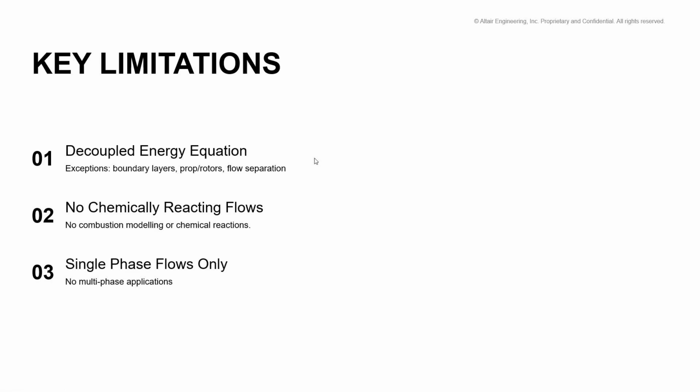Single phase flow only. If we are talking about flow in the air or undersea, that is possible right now. Even ships moving on the sea level, where we are talking about air separately and the water separately, but there are no multi-phase applications right now. But you can definitely go for ship kind of simulations as well, if you are talking about just the external aero and capturing the drag forces, lift forces and the pressure forces applied on the surfaces.